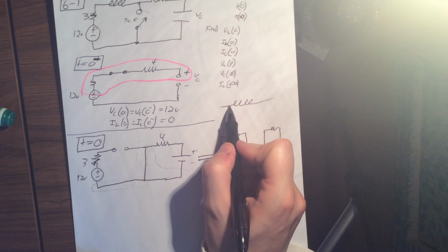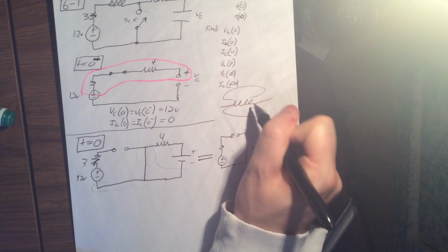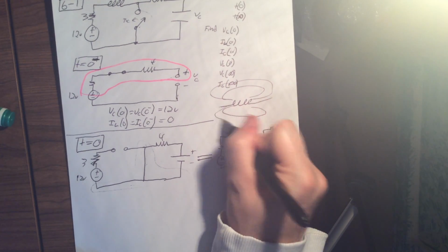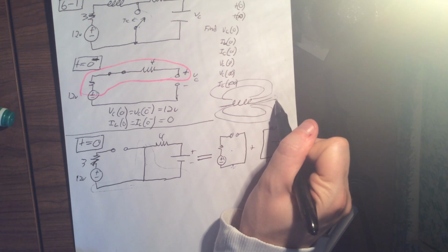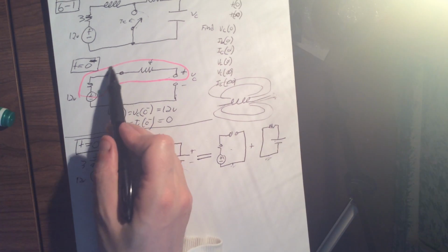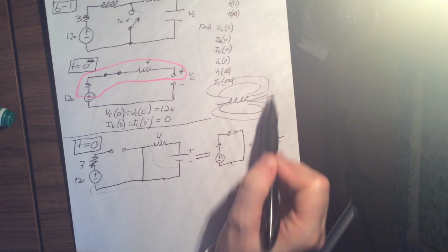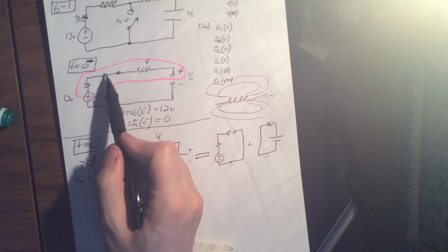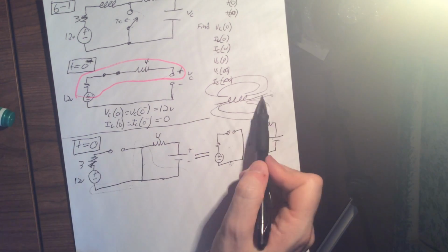As soon as I start pushing current through, all that current goes into starting to build these magnetic fields. As these fields build, they require less and less current, so more and more current goes through, which is why in the long term this field is totally built. Let's say this can only hold two of these lines, so this is 100% saturated. If that's 100% saturated, then it's just a wire, because all the current comes in, all the current comes out.